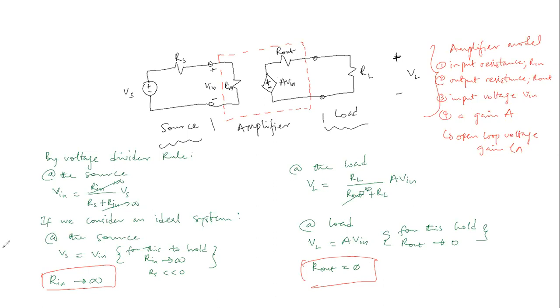Now, let us quickly consider the schematics before talking about the inverting and non-inverting configurations. Let us talk about the schematic representation of an operational amplifier. The operational amplifier is usually designated in this manner, where we have the power supply, and in most tests they are excluded. The power supply terminals are very necessary in the actual device because the amplified power comes from some external source.